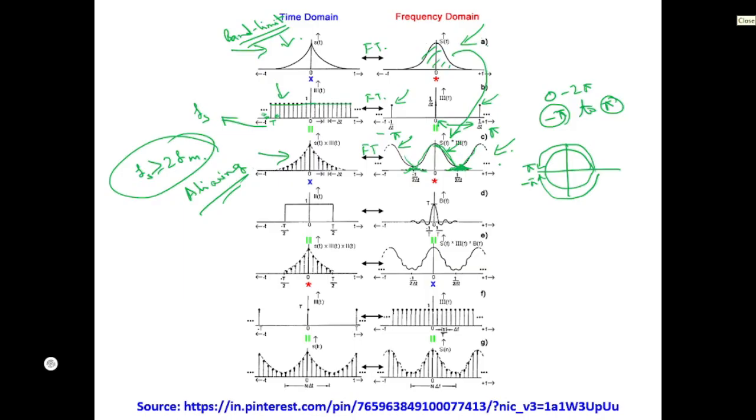Fourier transform. When you applied this Fourier transform, this frequency domain was continuous in nature, right? It was continuous in nature. So, what do we want now? We want this frequency domain signal to be sampled. Okay. So before sampling the time domain signal, what did we do? Band limiting. Now we have to sample the frequency domain signal. So what do we have to do? We have to time limit the signal.